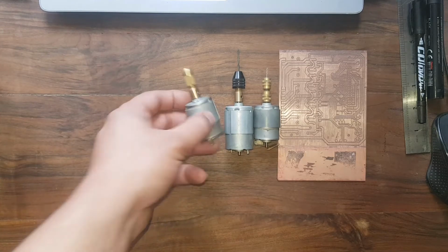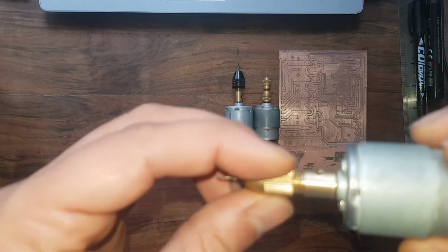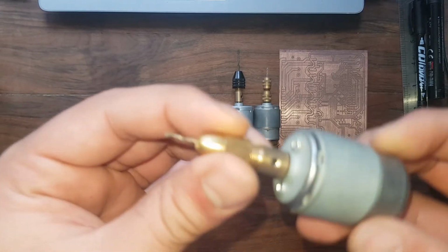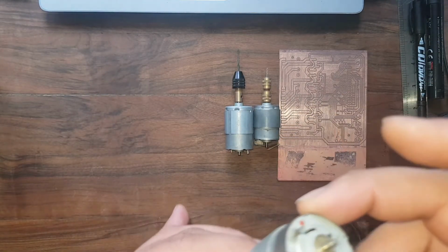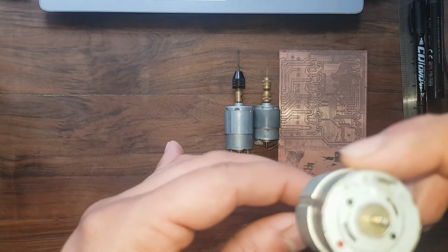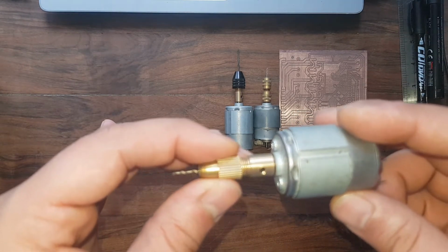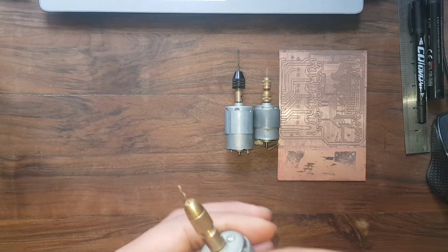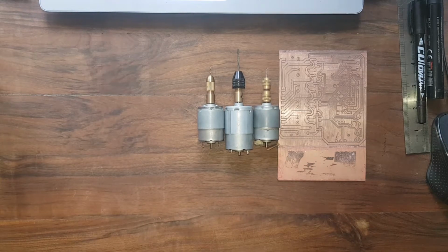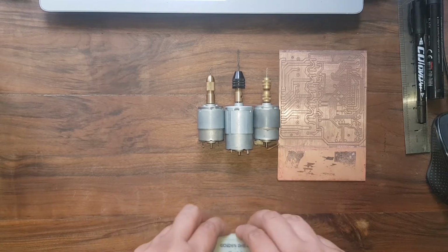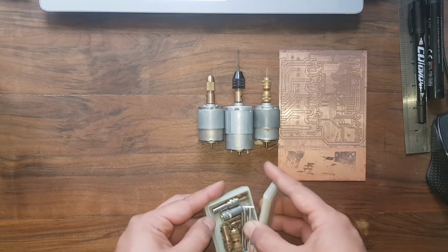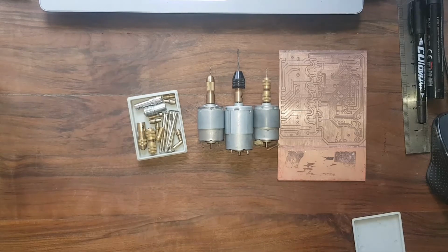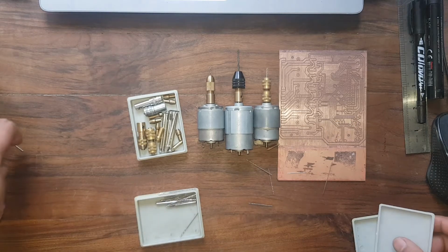It's really cheap, and you can just buy a DC electromotor and use it with your power supply, or just an adapter, and it doesn't matter how many volts it is. It just has to have enough speed and power to do your job. And of course you just need to buy some drill bits. Most of the drill bits you need in making a PCB are from 0.5 to maybe 1 or 2 mm.